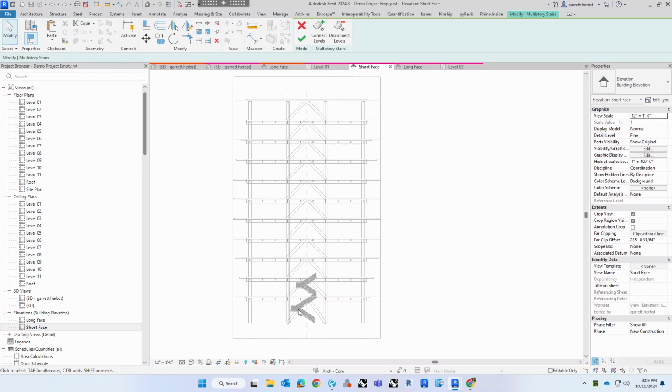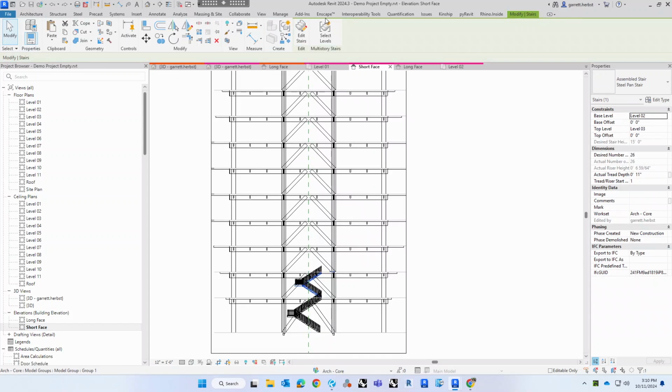But what it did is it pulled where the floor landing is going to be. So it kind of shifts things back and forth. Again, sometimes it works fine for what you're doing. Sometimes it doesn't. What we typically do, we just make sure that it's the same stair, and then we control the atypical stairs separately. And once you establish the multi-stair, you can also disconnect levels in case one level changes and you want to make that one a unique condition.